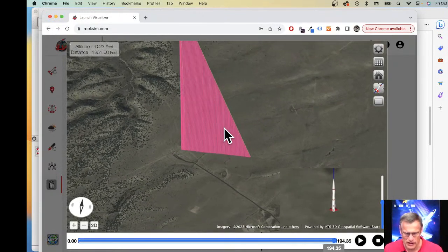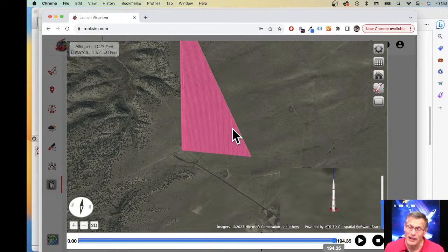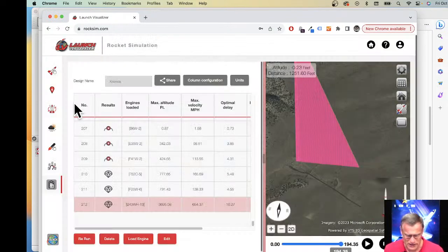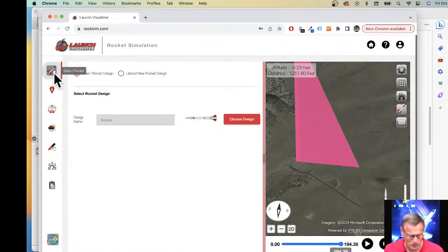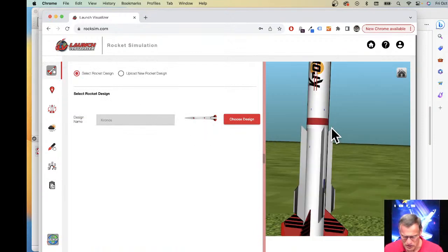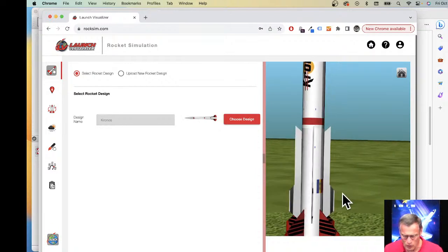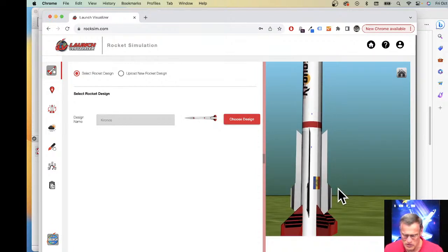So yeah, you could fly it on an I. It should be strong enough. It has plywood fins. They're through the wall. The rocket also has strakes on it. So what's a strake? If I go here, see these long fins along the side of the rocket. One of the reasons this is such a strong rocket is because of these strakes. Usually the weak point of the rocket is right in front of the fins.